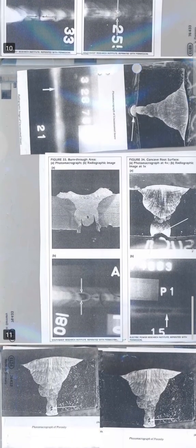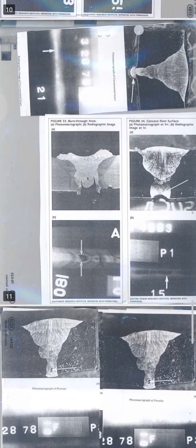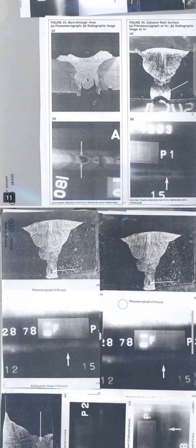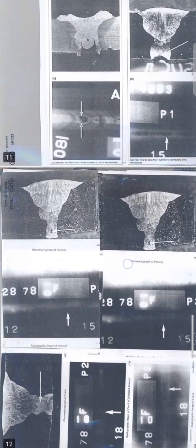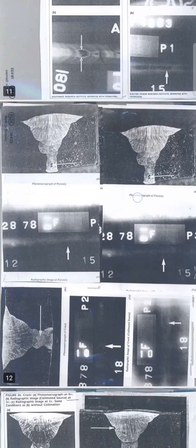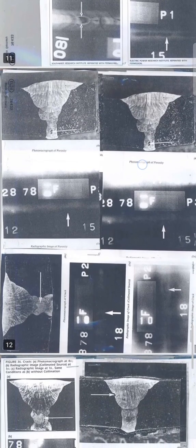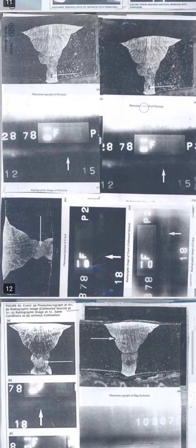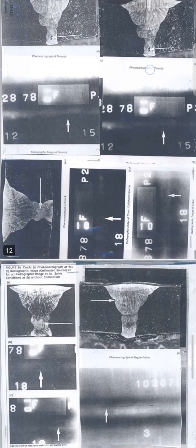outline on the radiograph. Burn-through results when too much heat causes excessive weld metal to penetrate the weld zone. Often lumps of metal sag through the weld, creating a thick globular condition on the back of the weld. These globs of metal are referred to as icicles. On a radiograph, burn-through appears as dark spots, which are often surrounded by light globular areas, icicles.